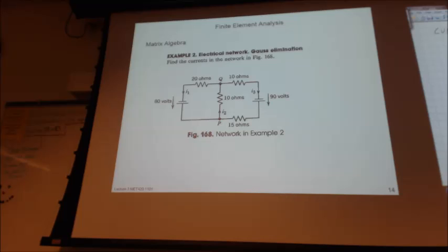So then if we look at node Q, how would we define node Q for I1? Is it going to be plus or minus? Minus. And then for I2, plus. And for I3, minus. Okay, so that takes care of the Kirchhoff part, at least as far as nodes P and Q. So now we can go back to the loops. It makes more sense if we start with the nodes instead of the loops like I was talking about.